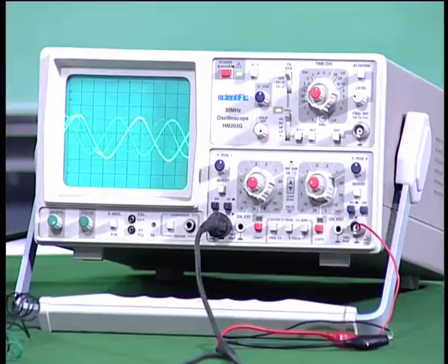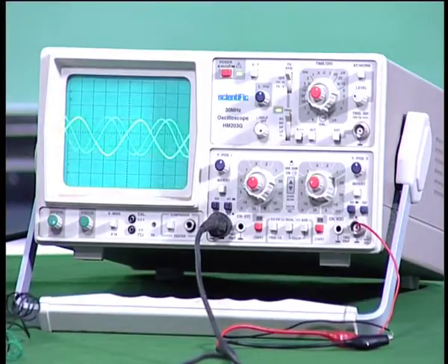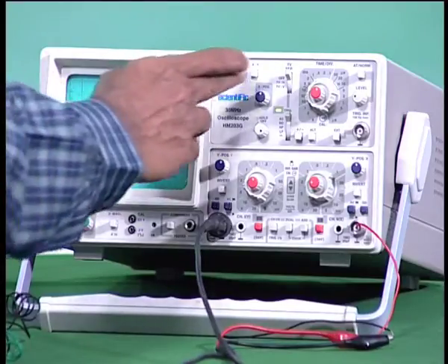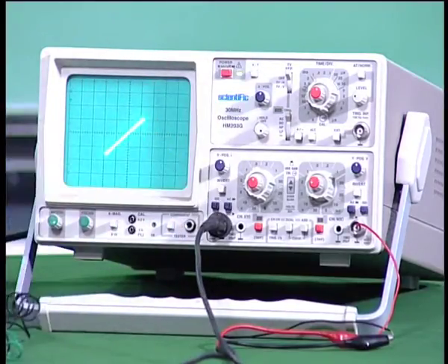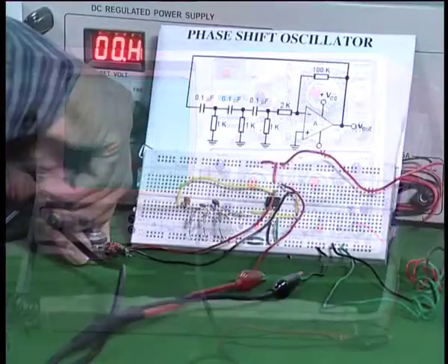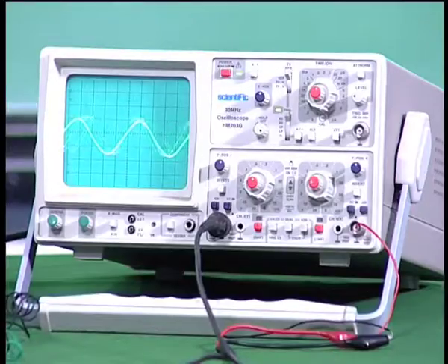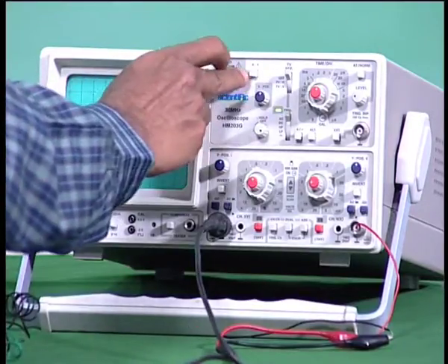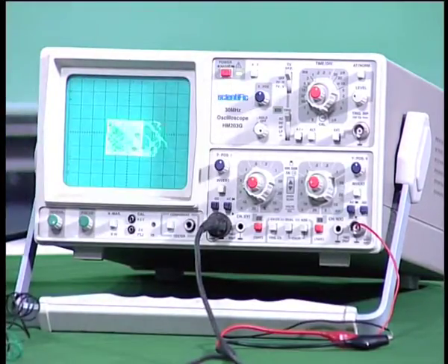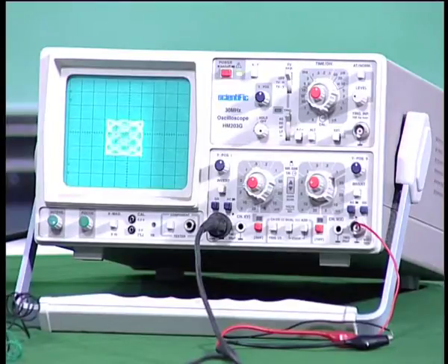output from the circuit that I get on the oscilloscope, and that is what I now see when I change it to XY mode, you would find a straight line. Let me get the waveform back and then adjust the frequency in the XY mode. I am now making it X and Y and trying to adjust till I get a circle. I should try with this.